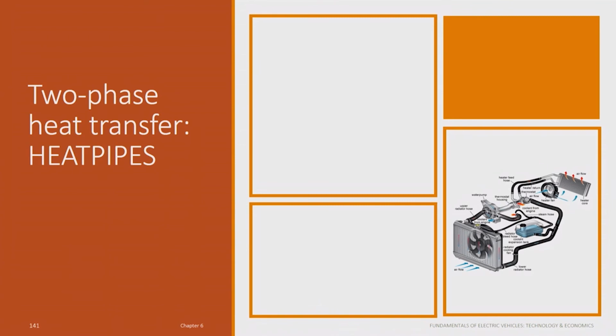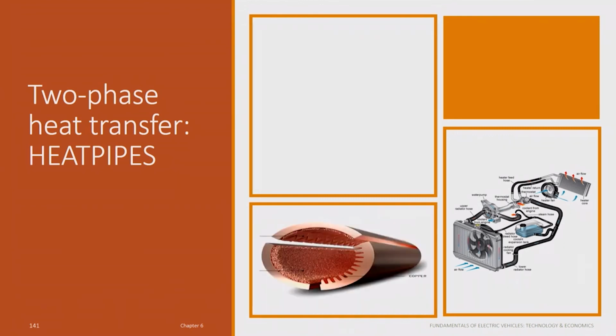There are valves, there are hoses, there will be leakages, there have to be filters, you have to make sure there is no corrosion over time, lot of things. There will be pumps. So the pump will require a motor. So, to cool a motor using another motor, that is the kind of thing. So, we used what is called two-phase heat transfer.